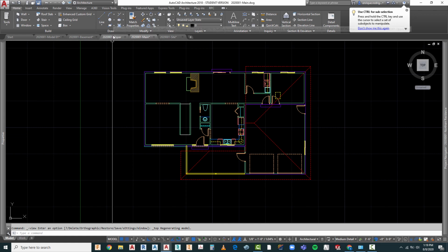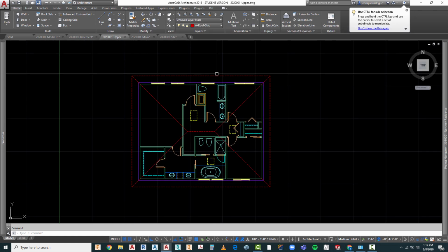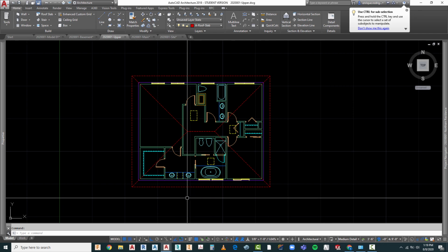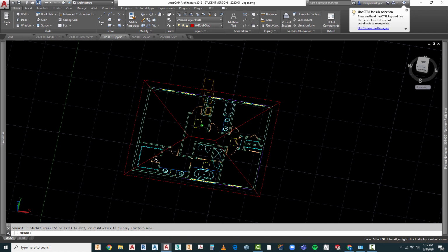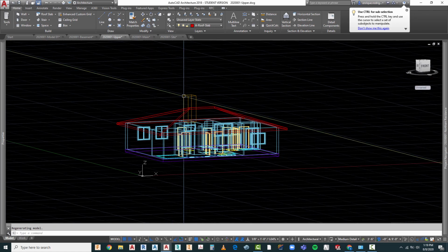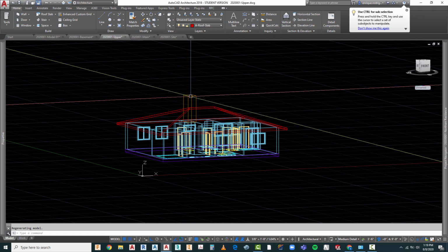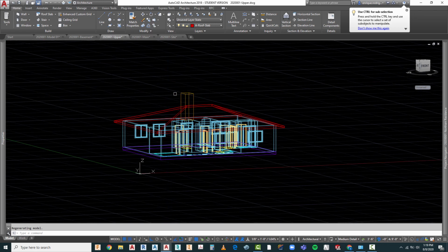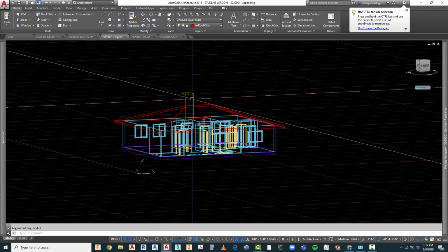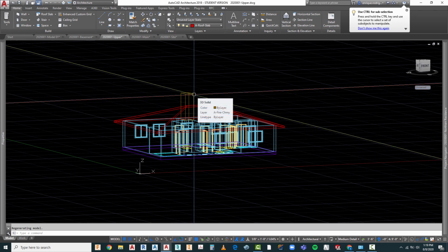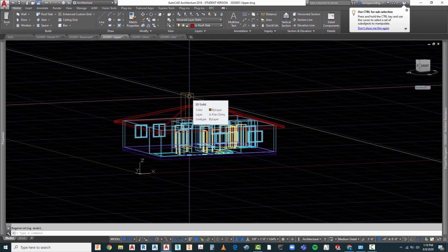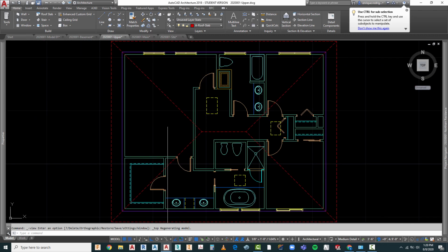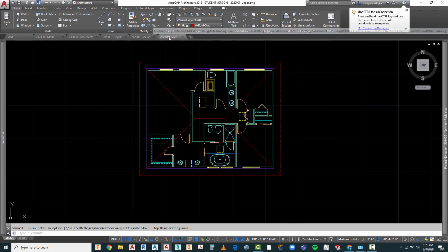Let's go ahead and go to the upper. I already mentioned some of the things that we need to do with the fascia board and potential gutters for that. If we again go to 3D modeling, this is where we would be doing the 3D modeling for the trim work and anything we would add up in here for our chimney cap that we might do. Now a lot of this we're going to want to do in 2D line work, but we're going to definitely need to give unique layers to them so that we do not run into the problem of, when we go to present it in plan view on our sheets, seeing three-dimensional excess lines in a number of places. So let's go ahead and go to the site.